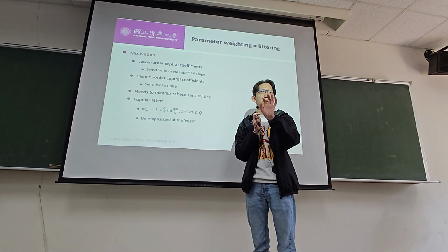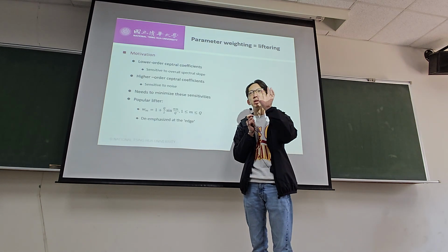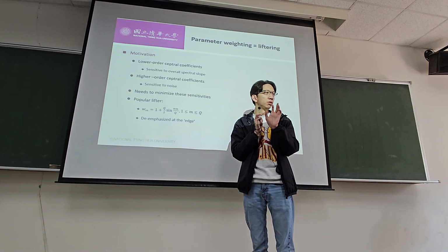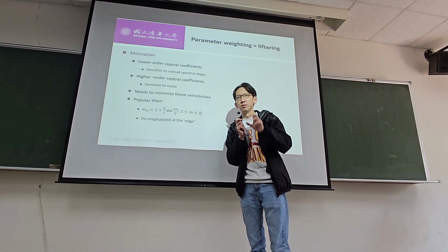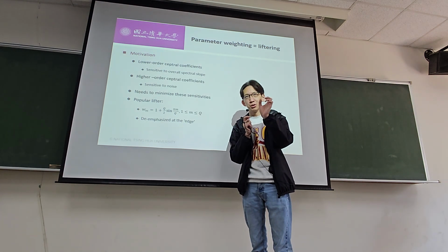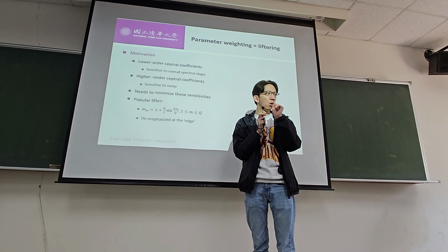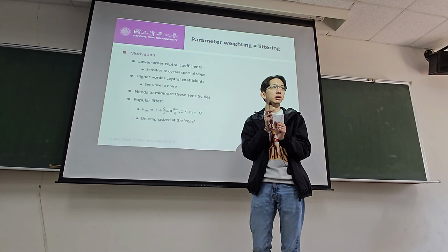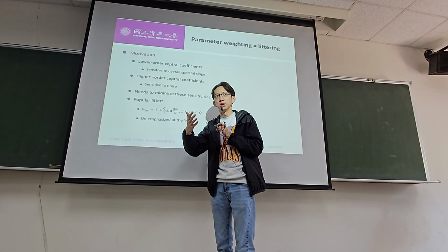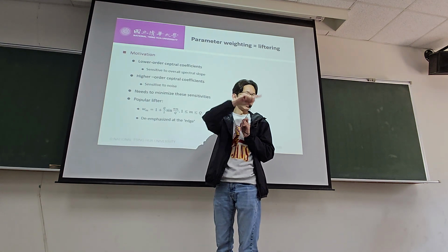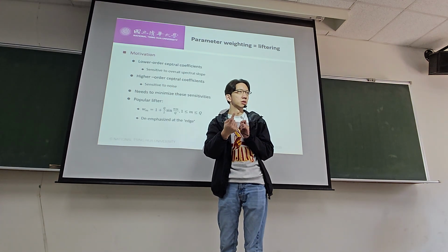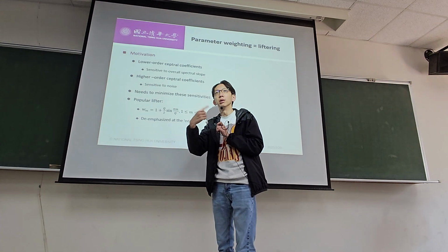Always remember that whenever you pick a segment, you are multiplying by a windowing function. So in the future, if you do any work in your lab or wherever, as long as it's a signal kind of thing, you should choose a segment and then do some analysis, and you have already changed the frequency components. The same applies to cepstrum coefficients. The cepstrum is essentially a pseudo time domain, because you take the spectrum representation, take a log, and take the inverse spectrum representation. So it's like time domain, but not the real time domain.